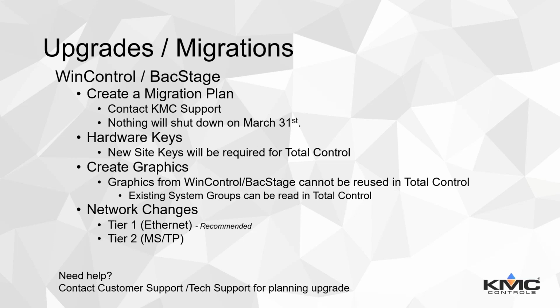What that did was put all the points you wanted on your graphic into a tabular form so that all those points are read quickly and together to make the graphics work well. The system group portion that was created can be reused and read in TotalControl. I'll give an example of that later in the demonstration, but I want you to know that optimization can still transcend into TotalControl. However, the individual graphics and the images cannot.